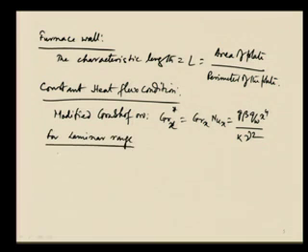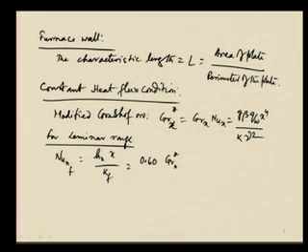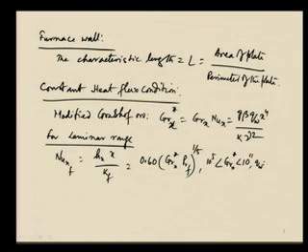The correlation is that Nu_x, evaluated at film temperature, which is equal to h_x x by k_f, is equal to 0.60 into Gr_x star, the modified one, into Pr_f, whole to the power 1/5, where 10 to the power 5 is less than Gr_x star less than 10 to the power 11, and q_w is equal to constant.